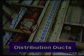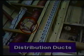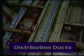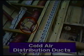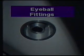Tubing performing the same function within the cabin is usually referred to as distribution ducts, again including the type of air contained in the duct, such as cold air distribution duct. The red, flexible, wire-supported ducts used in the system are usually called skeet hoses, or skeet for short. The control units, located near each passenger seat, are called cold air eyeballs, or eyeball fittings.